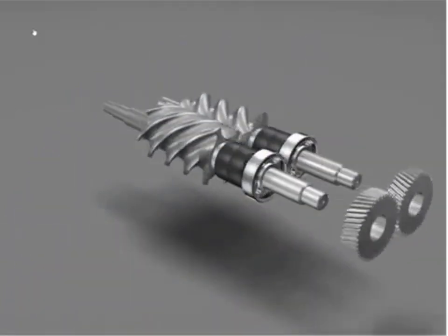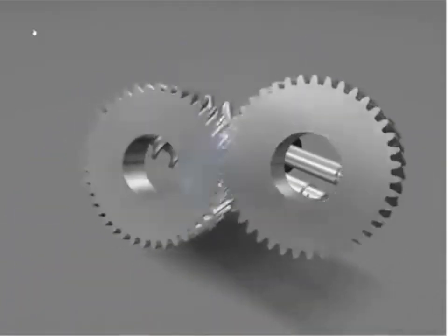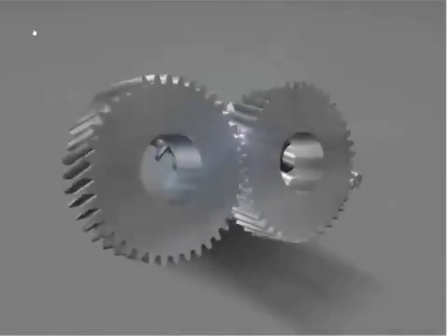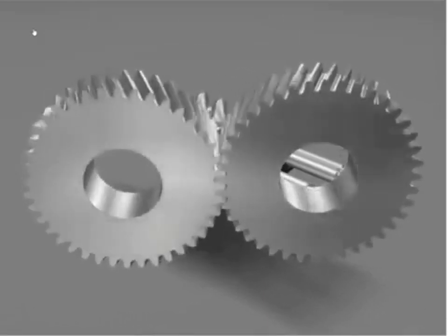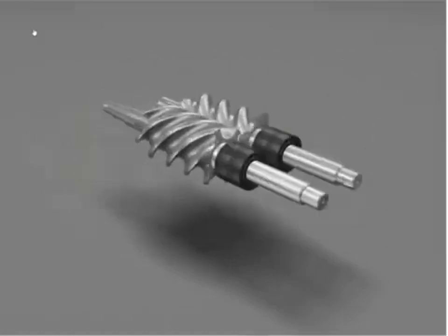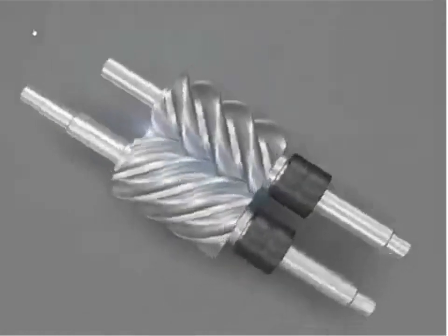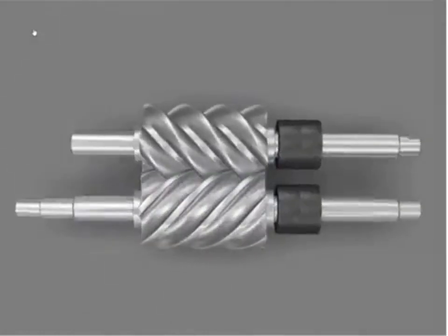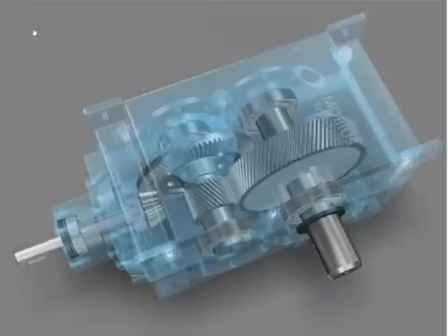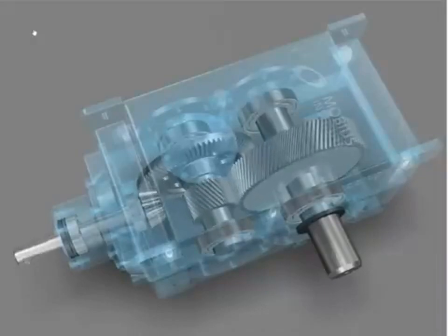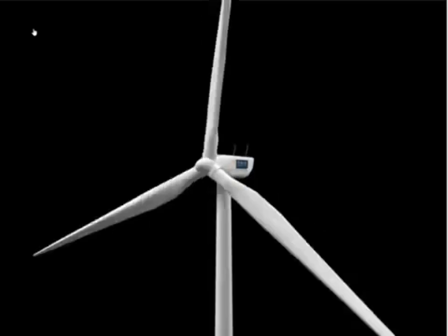The same can be said for timing gears or normal gears in a gearbox. As those teeth mesh together, they create a vibration pattern, and if there's a problem with the misalignment of the teeth or anything else, it creates a vibration pattern. And that goes for almost every rotating component. In the case of our more sophisticated gearbox, the vibration, I should say, is more complicated, but we can still diagnose an awful lot from a machine like this.